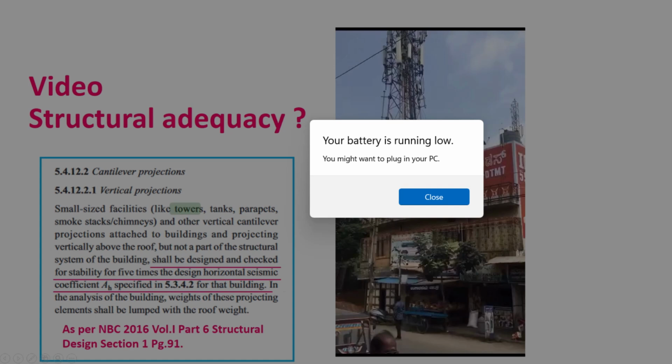Okay. So ultimately, just to tell you that this particular structure has fallen down because in this building, all these activities they have done, they have erected a small structure on the slab itself, because it is not an integral part of the column itself, and they have erected the structure and the entire cantilever structure is on it. So this has caused the problem. I suppose you must be very careful in case you are planning this type of thing onto an existing building.